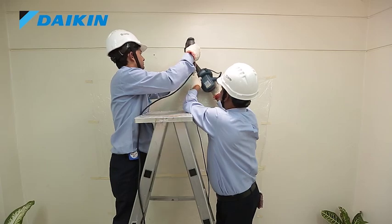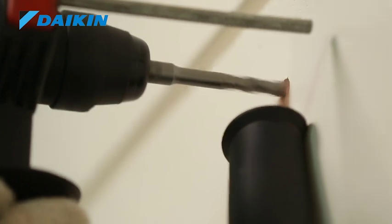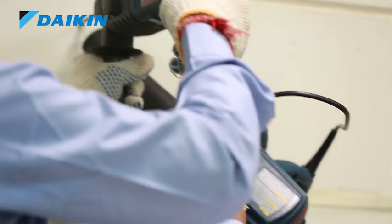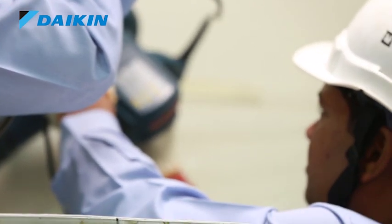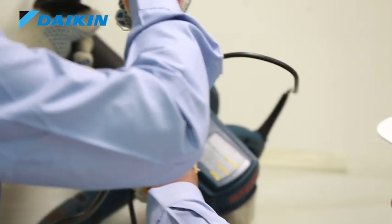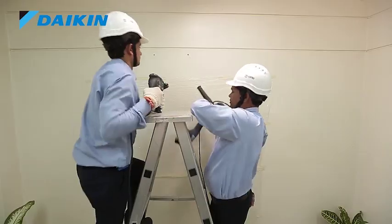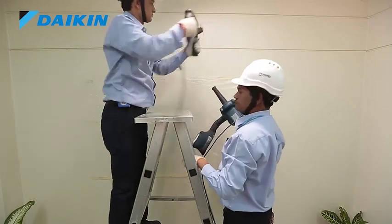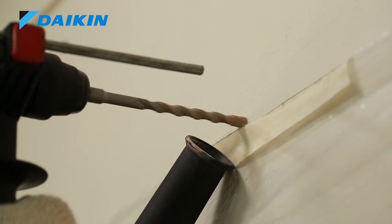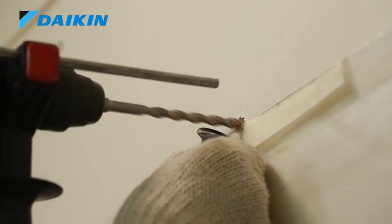Now, using a drilling machine, drill holes in the wall at the marked points. While drilling the hole, you should use a vacuum cleaner to suck the dust coming from the wall. Also, make sure there is no electrical conduit or electrical junction box backside of the wall, which may lead to fire. Also make sure there is no drain pipe.